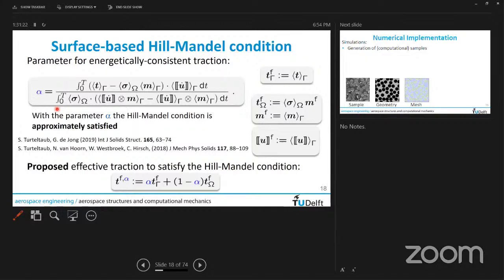From your microscale simulations, you are trying to get an effective traction separation law. Now, at what length scale would this effective traction separation law be valid? For example, if you have diffuse cracking in the composite, would it still hold? Because there should be a length scale involved in your effective traction separation law.